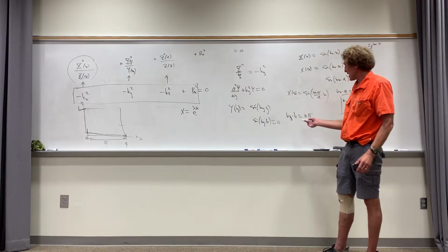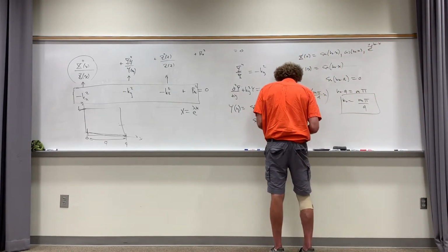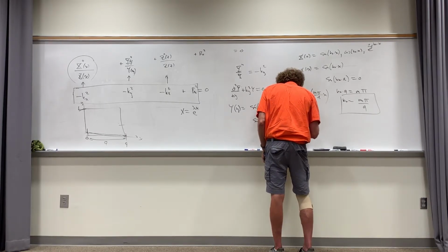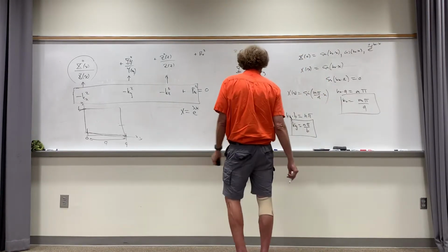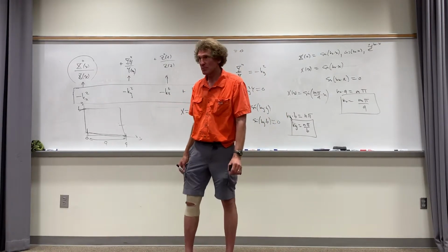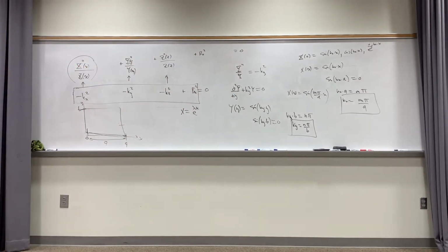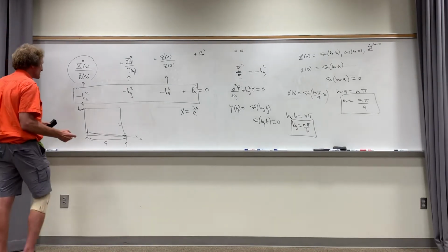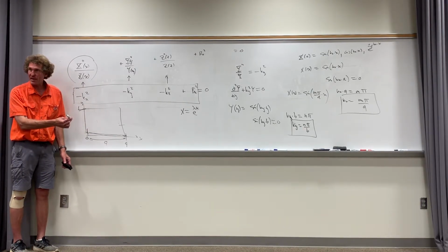And therefore we can get ky is simply equal to n pi over b. And lo and behold, that works. So now I have my variation on y defined. Now for the variation on z. This is the important one. X and y are just sinusoidal variations in terms of the magnitude of the Ez component of the electric field. But now if you think about this, remember, we have an E field in the z direction, right? We have to figure out a way to get the boundaries for that.